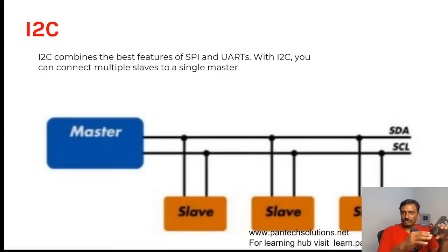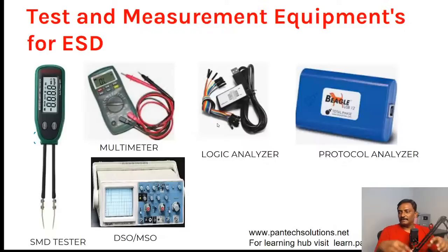So for today, you just need to know what UART is: a serial communication device which can communicate between two devices at a time. With SPI, the more devices you have, the more GPIOs you need, but it's much faster than I2C. With I2C, you could connect more than 1,000 devices using these two wires, and anything can act as a master or a slave. But with SPI, only one can act as a master, and you could have multiple slaves. Is that clear? Let's go for the next one.